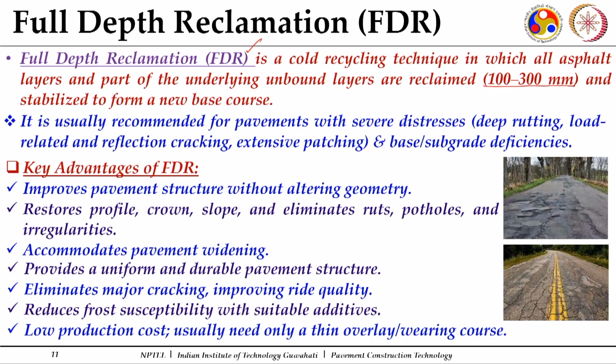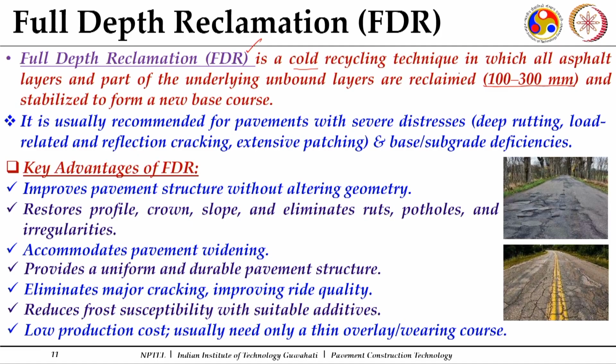So, this is an advantage in full depth reclamation: in addition to the bound courses, we are going to address any issues with the unbound courses, and then these unbound and bound courses together, whether along with a requirement of virgin aggregates or not, and the recycling agents will be used to produce a stabilized base course. So, full depth reclamation is a cold recycling technique in which all asphalt layers and part of the underlying unbound layer are reclaimed and stabilized to form a new base course. This is what this specific thing is.